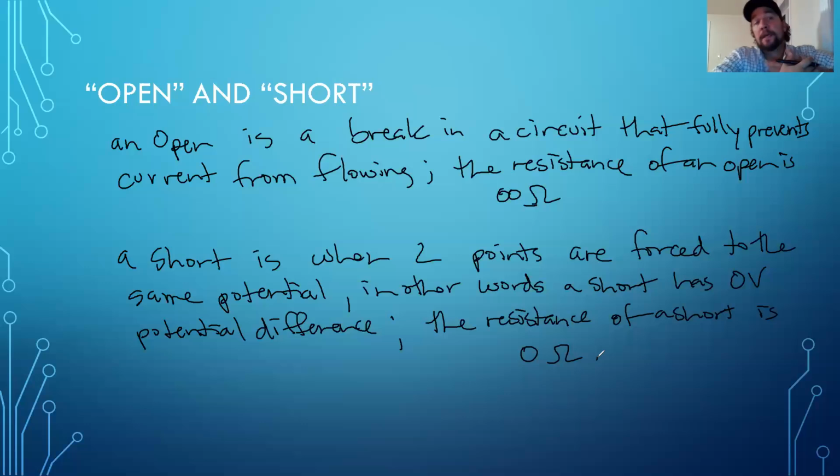All right. A short, on the other hand, if we've got a series circuit, well, we can calculate what current we're expecting. And we know that as the total resistance goes down, based on Ohm's law, the total voltage stays the same because we're not adjusting it. If my resistance goes down, then the current goes up.